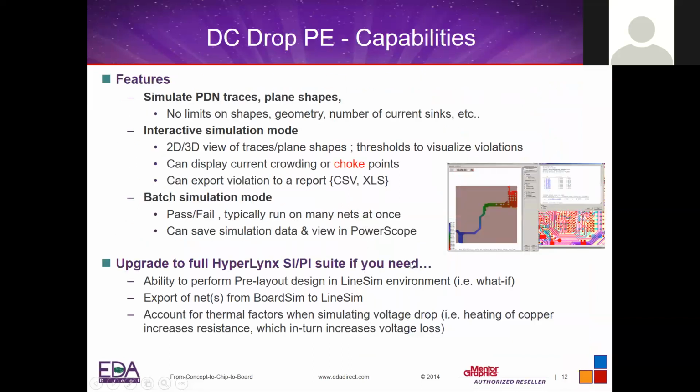Okay, and then it can certainly simulate the traces and the plane shapes. You can do a 3D, 2D view, can identify choke points, and if later on you want more capabilities in this kind of design, you can always add the ability to do the decoupling analysis and the ability to edit this plane structure while you are analyzing without going back to layout.